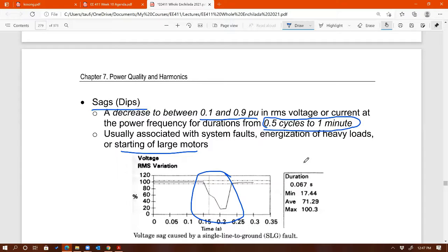And the effect of that physically would be that the inductors, keep in mind that rotors and stators are just inductors, windings with a magnetic core. At the beginning, since flux is not yet being produced, these inductors, quote unquote inductors, are acting like a short. Imagine you have a coil around a magnetic core, but there's no flux yet. How can you induce voltage if you don't have any flux?